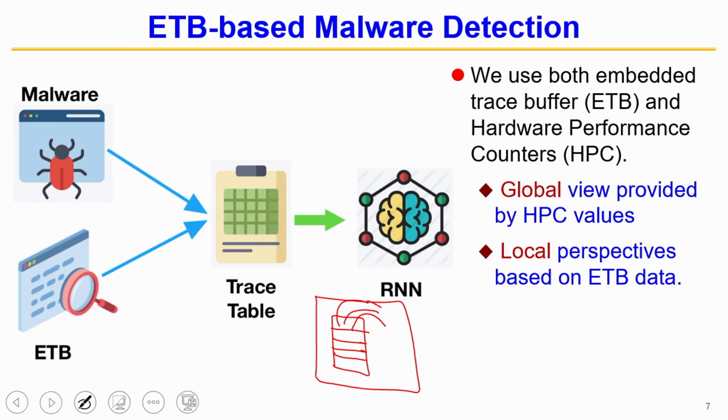This is typically in the order of 128 signals, and in the order of 1024 clock cycles. It is a very small number of signals, 128 out of millions or billions of signals would be traced and stored. There is a trade off, I will come to that in a moment.